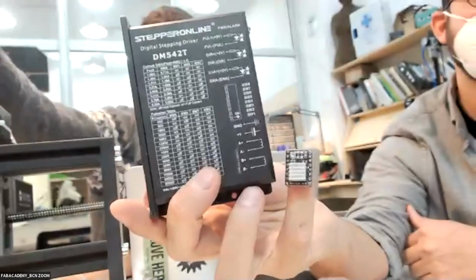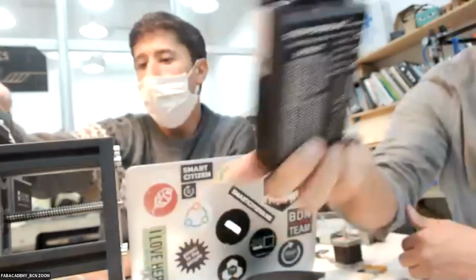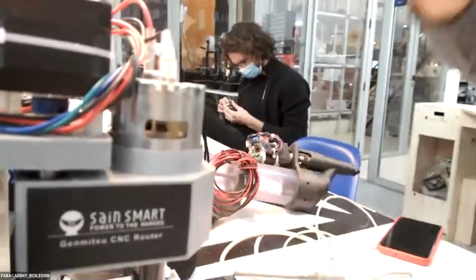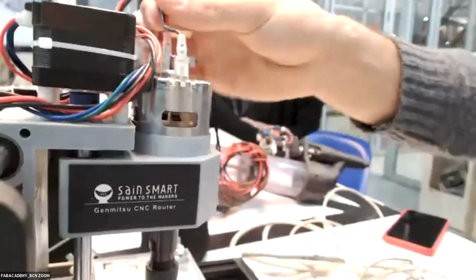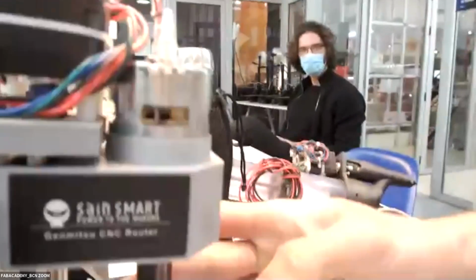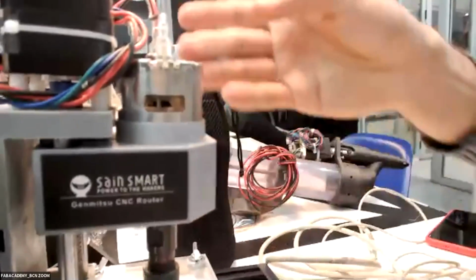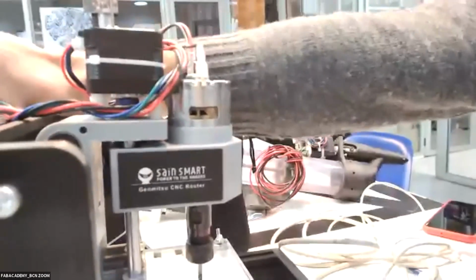Now, these other ones, you can control them with just 2 cables, but you use the technique we talked about, and we will see in outputs, called PWM, which is you just have an average voltage based on the amount of time that you're on versus the amount of time that you're off. And you just put 12 volts, but with on, off, on, off, on, off, and you regulate the speed because of that. All that is put into an electronics box that runs a little piece of code inside.